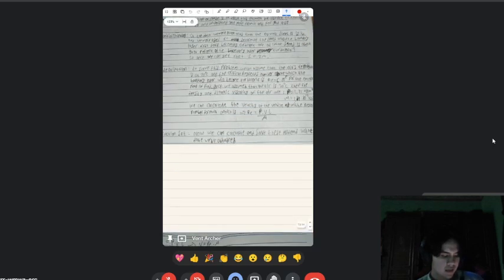Once we assume the air is 20 degrees Celsius, we can look up the density and dynamic viscosity in the table: the density is 1.221 kilograms per meter cubed, and the dynamic viscosity is 1.81 times 10 to the power of negative 5. Then we can calculate the velocity of the vehicle by modifying the Reynolds number formula to get the formula for the velocity.